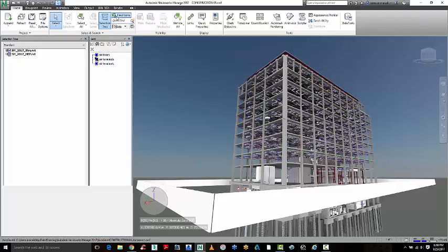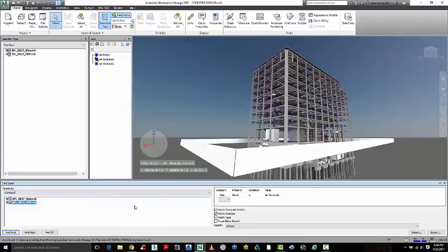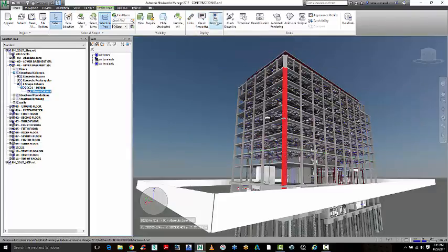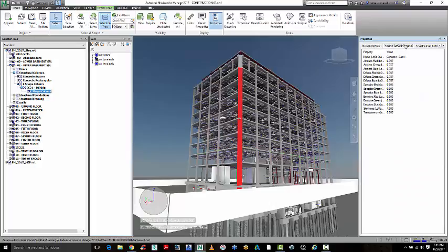Plus we have a tool called Find Items that allows us to find all the information in the model based on certain properties. We have quick properties and properties available here, so if you want to find out information on a certain object, you're going to be able to read all this data that's embedded within that particular element from the authoring tool.